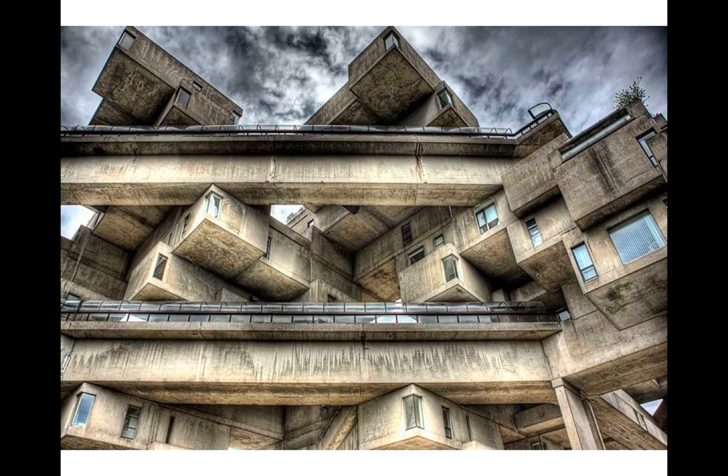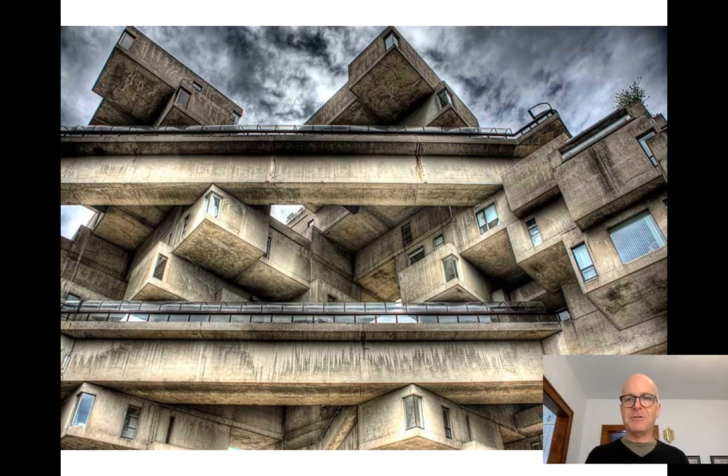And here a more contemporary image looking up. The bridges are actually poured in place. Those are the circulation, but also the main structural frame. And then you can see, using post-tensioning, how these elements can cantilever out and create some of those overhangs in spaces. The weathering you see is 40, 45 years of rain and snow and ice. The quality of the concrete, the coloring of the concrete, the consistency, as you can see, is much better than you would normally expect in an in situ project, right? This is all because of the quality control that you get in precasting.